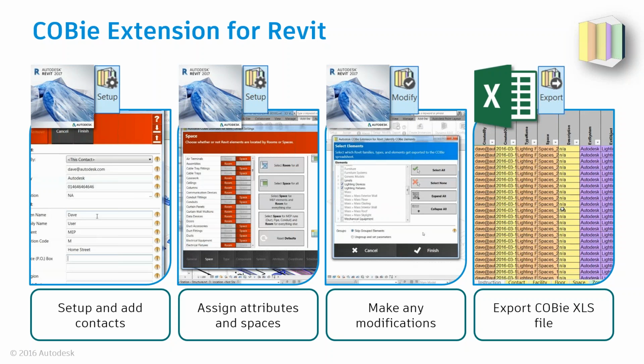So on the building side, we have a COBie extension for Revit. This has been available for quite a while now. For those who are aware of it, great, have another look, because we've made some big improvements to that, allowing you to do additional mappings. For those who aren't aware, we will provide you with a link at the end of this webinar. This allows you to create COBie parameter fields within your Revit model against any object, populate that from the Revit data, and then export out to that COBie spreadsheet after doing mappings to particular zones or spaces.